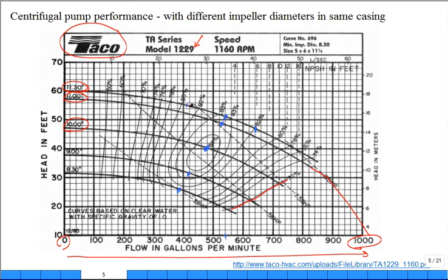This is the region that I really want to run that pump. I really don't want to run it elsewhere. You just start falling off on efficiency. And then you would get a whole suite like that. That's where you would want to run that pump. Don't be trying to go down in this region or any other region. Just try to run it in this shaded region. Okay? You would be changing impellers to change some of it.